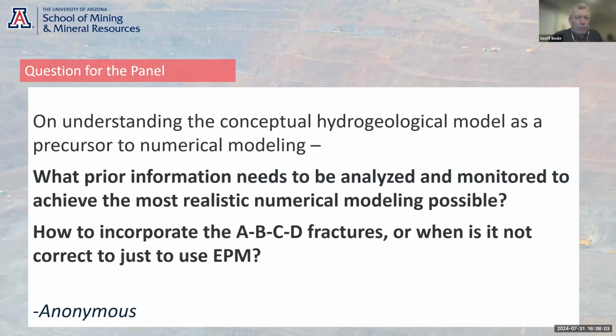Well, okay, I'll give it a go. What prior information needs to be analyzed and monitored? Really the key thing with a numerical model that helps you validate it is if you have some piezometer responses to stress, i.e. long-term pumping trials or excavating the pit, then you can calibrate the model.